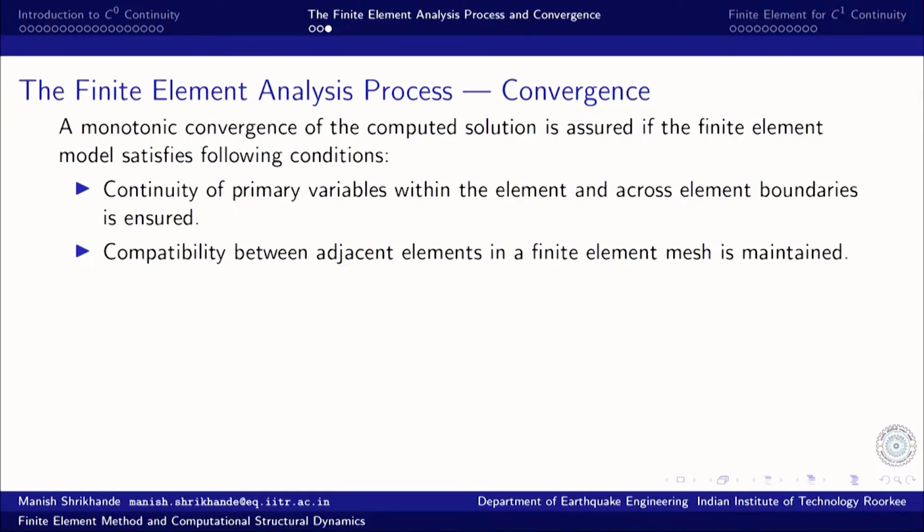So, the second thing is compatibility between adjacent elements. Again, in a finite element mesh, there should not be any gaps or even overlap. So, for domain compatibility, there should not be any under representation or over representation of the domain of the original problem while discretizing it into the finite element mesh. Then